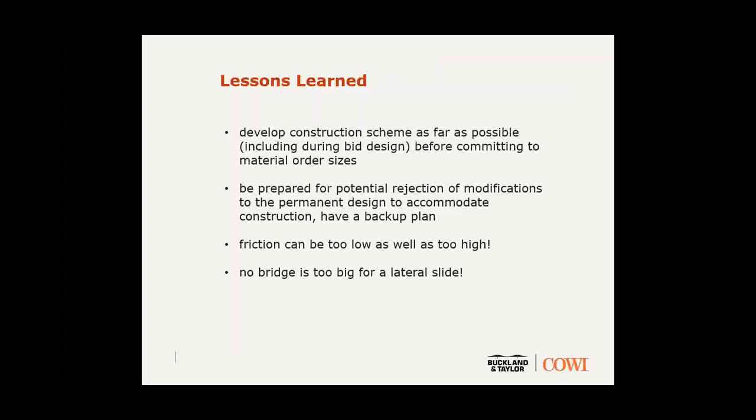Be prepared for potential rejection of modifications that may affect a permanent design, something you want to do to accommodate construction, and have a backup plan for that. We had one idea on embedding the sliding girders in the piers. It just wasn't acceptable to the owner in the end, and that meant a bit of scrambling when it came time to design the sliding girders to accommodate that requirement.